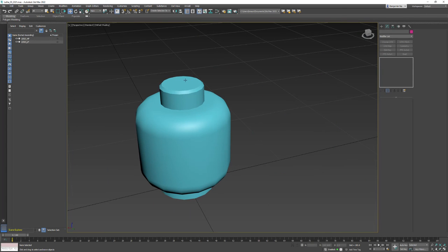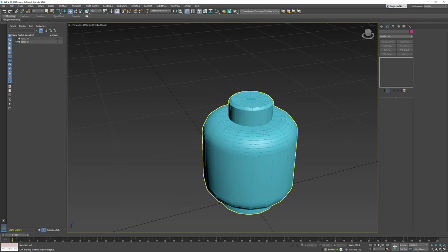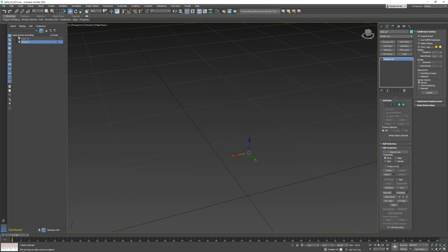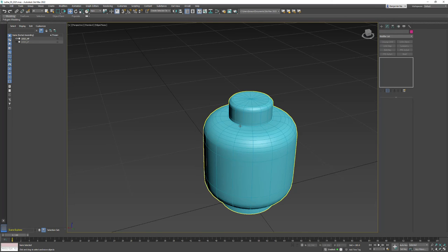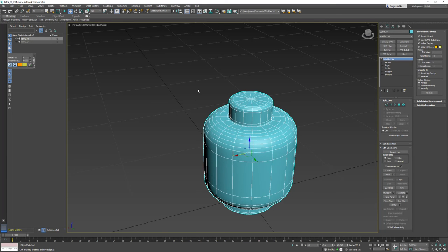Let's delete this test one. And they need to sit within the same location. Like here's my low poly, and here's my high poly. Now we're going to use these high poly, low poly models for texture generation in the weeks to come. So we're going to practice this process of making high-res meshes. So you'll want to save this, and you're going to want to turn this in. And remember, the important thing is make sure that when you're working with NURMS, you're working on unique objects and not instances, and that you're also naming your objects and keeping them organized.